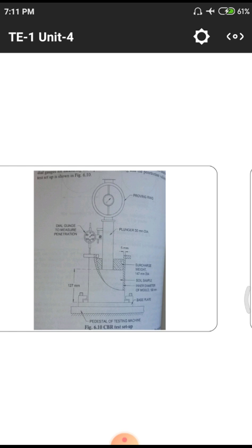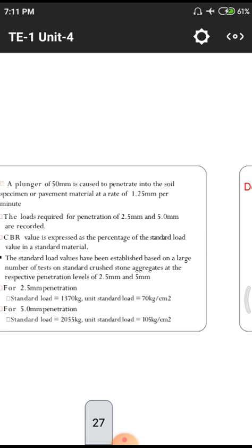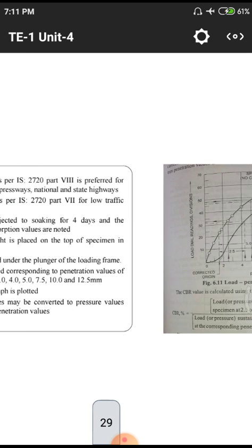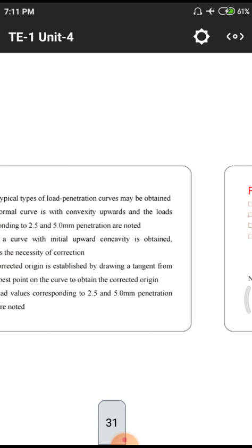On one hand, we apply some pressure on the soil sample using this plunger rod, and that pressure is observed with the help of the top dial gauge. At the same time, we need to observe what pressure is being applied on the soil sample, and the displacement also with the help of the dial gauges, so that those two will help to find the bearing pressure of a soil.